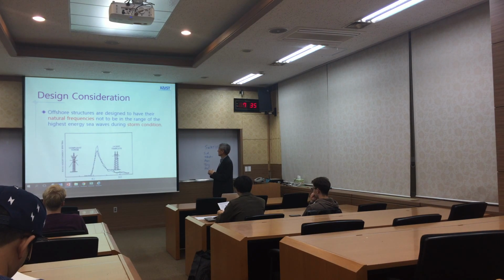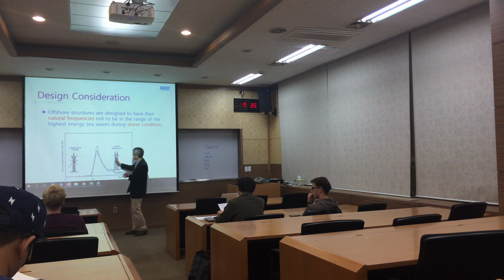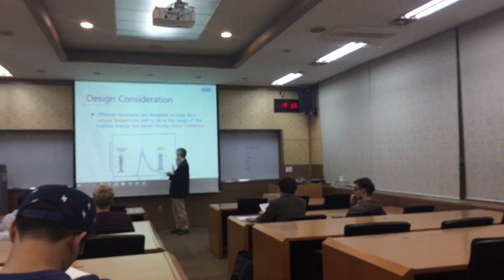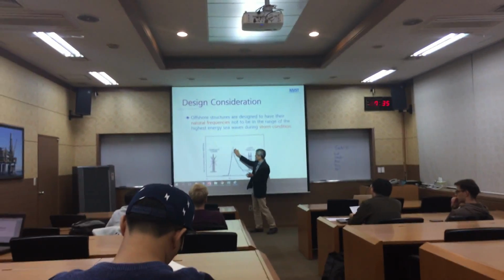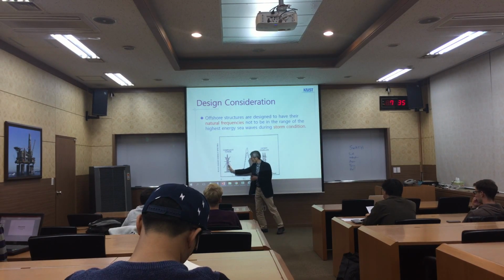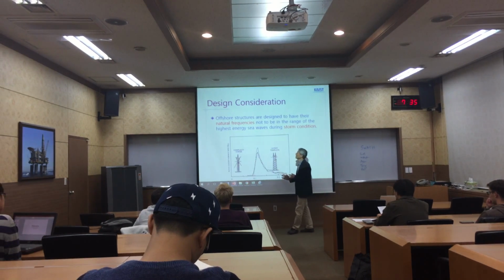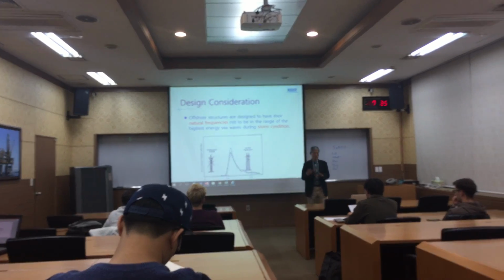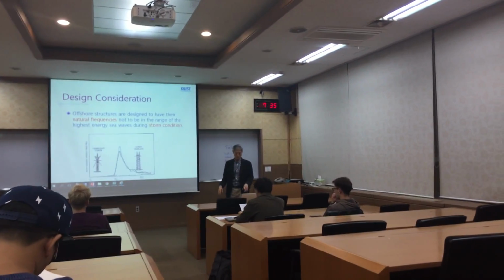Design consideration. The natural frequency of the motion, heaving, or other six degrees of freedom should be off the wave frequency. So some designs can be above the period of high frequency waves, or lower. So you need to avoid resonance of motions.